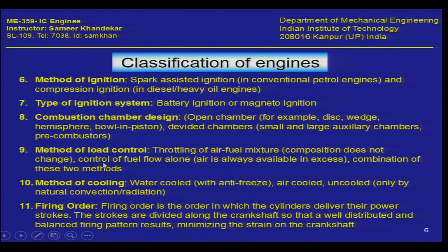Of course, you can also control the fuel flow alone, that means the amount of air remains constant, typically in a diesel engine that is the situation, and only the amount of fuel, that is the diesel, is what you control, or you can also do a combination of these two methods. The cooling methodology: in small engines, for example a motorcycle engine, you have seen that they are air cooled, but the larger engines are all water cooled. So you can have water cooled engines with some antifreeze material added to it, so that the water does not freeze in negative temperatures, for example.